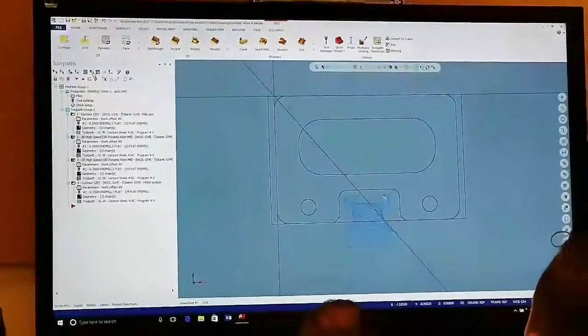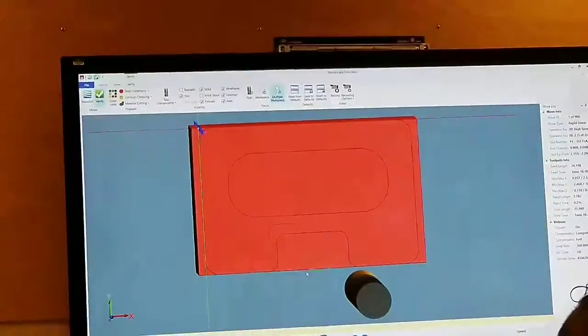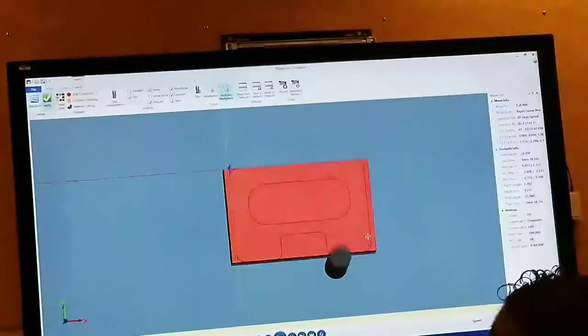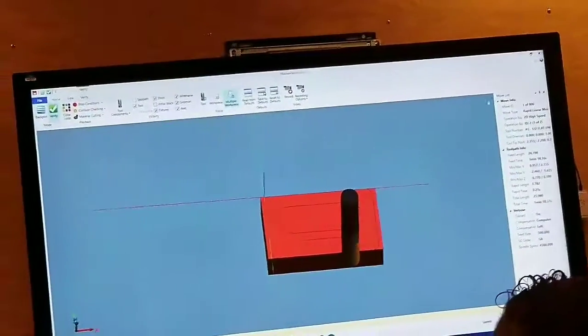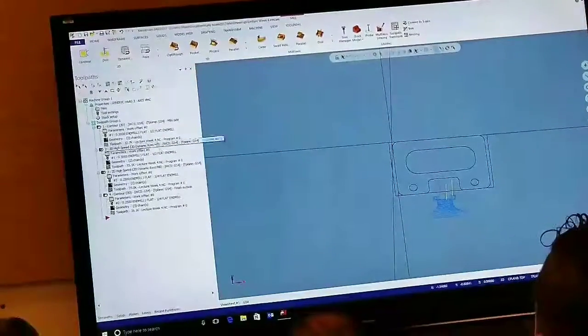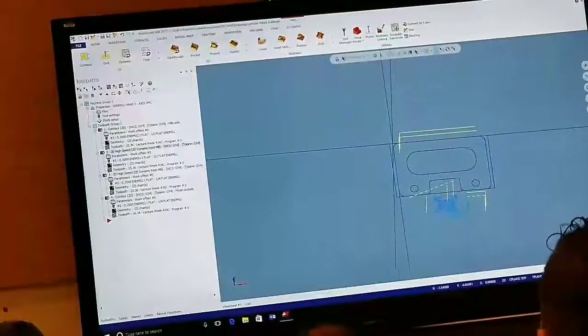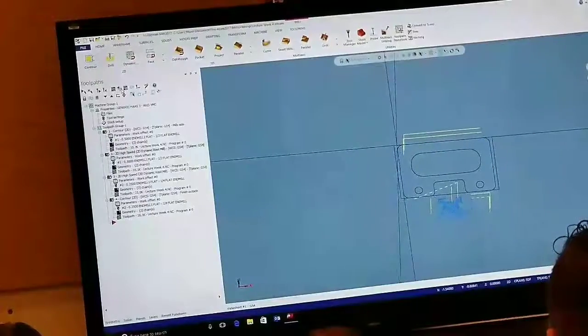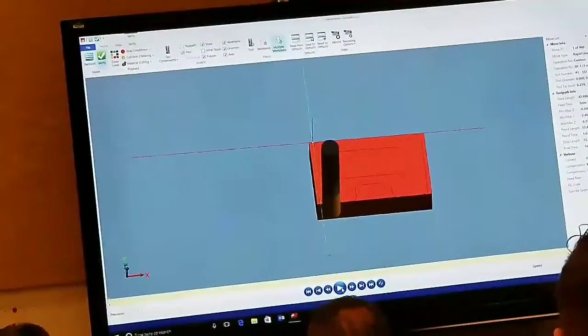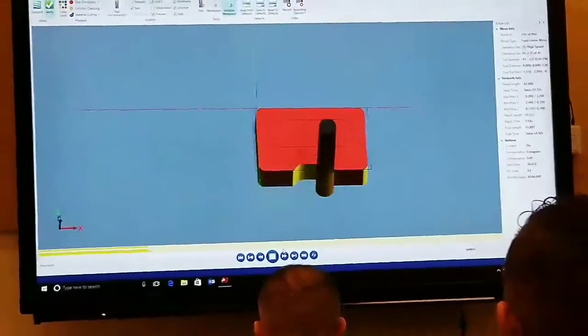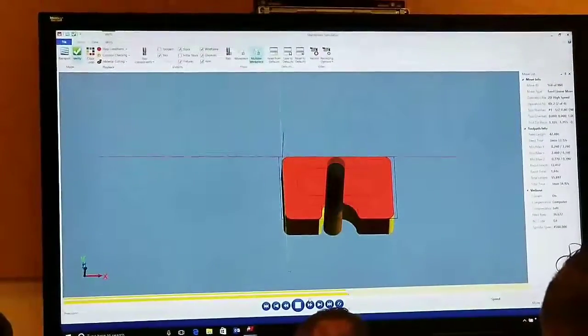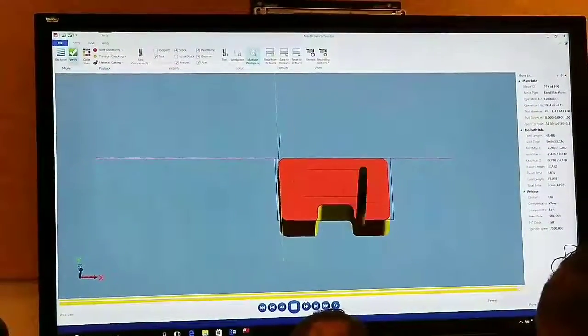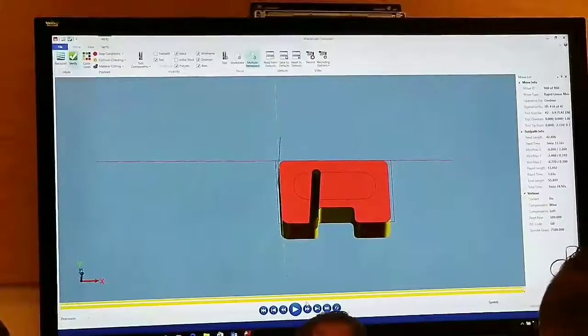Regenerate it all. Now it's all there. Now we're going to verify it. Watch it. Select all your toolpaths. The first one was unchecked. Yeah, it's just going to do the dynamic. There it is. Okay, there we go. All selected. Verify, and now we'll watch it. So we'll hit play here. We can watch it mill. It roughs away there. Comes in, then the smaller one roughs out the corners, then it comes back and finishes the whole thing. It happens like lightning.